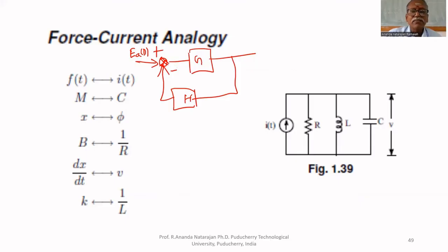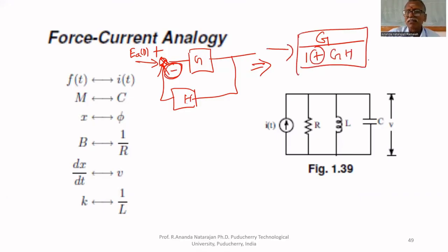So negative feedback. If you have the block diagram like this, and I want to remove this feedback, to make this as a single block, this is equal to G upon 1 plus. If you have a minus sign here, you write 1 plus. This plus sign is because of this minus sign. Negative feedback means 1 plus GH. So you can find a single block like this.